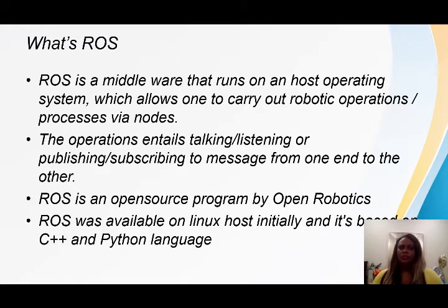Nodes can take care of a small subset of tasks, for example, reading a sensor or controlling a servo. Those nodes connect together. What does this mean? Nodes have information to share, and they share the information using, for instance, a topic. If another node is interested in that topic of information, it subscribes to that topic and reads the information.